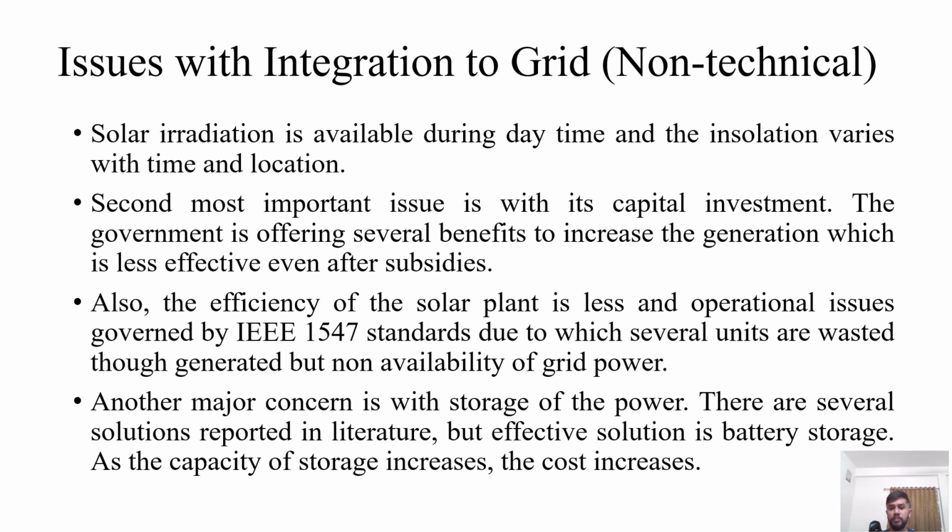Second most important issue is capital investment. The government is offering several benefits and subsidies to increase generation with the help of these renewable energy resources, but it is less effective even after subsidies because the capital investment cost is very high. Also, the efficiency of the solar power plant is very low, and the operational issues are governed by IEEE 1547 standards, due to which several units are wasted. Though generated, they are not available because, as per the IEEE 1547 standards, a plant below 5 megawatt is shut down when grid power is not available.